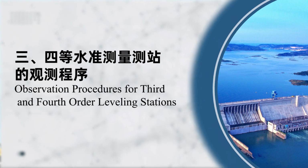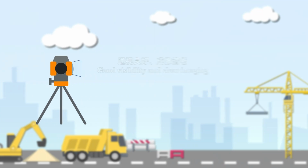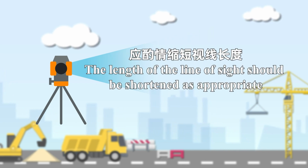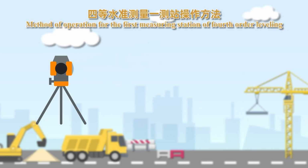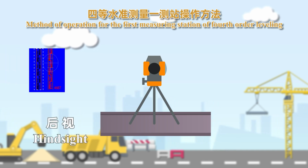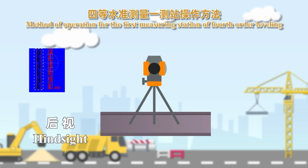Next, we will learn the observation procedures of 3 and 4 leveling stations. The observation of 3 and 4 leveling measurements should be carried out under the condition of good visibility and clear and stable imaging. If the imaging is not good, the line of sight length should be shortened as appropriate. The operation methods of the first station of 4 leveling measurement are as follows. 1. Place the leveling instrument in an appropriate position and roughly level it. 2. After alignment, the black surface of the leveling rod is viewed, and the upper wire, middle wire, and lower wire readings are read respectively after the instrument is accurately leveled.